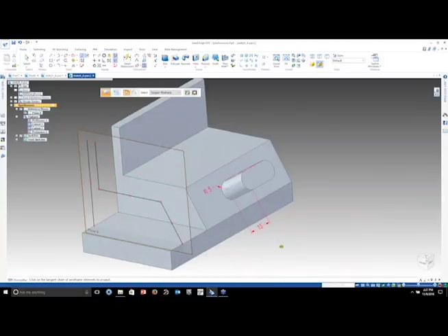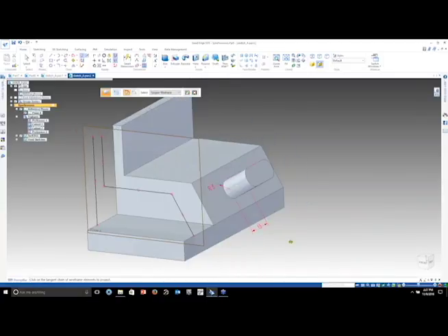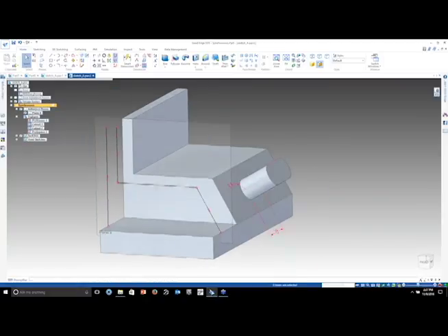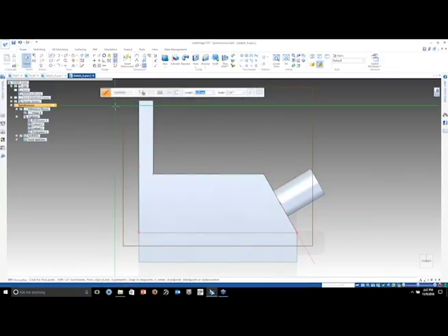You're going to wear out your F3 key and escape. You hit those a lot. All right, so hit F3. I'm locked to a reference plane. Maybe I want to project with an offset. You know, this one I want to make it exact, so I'm just going to say OK.